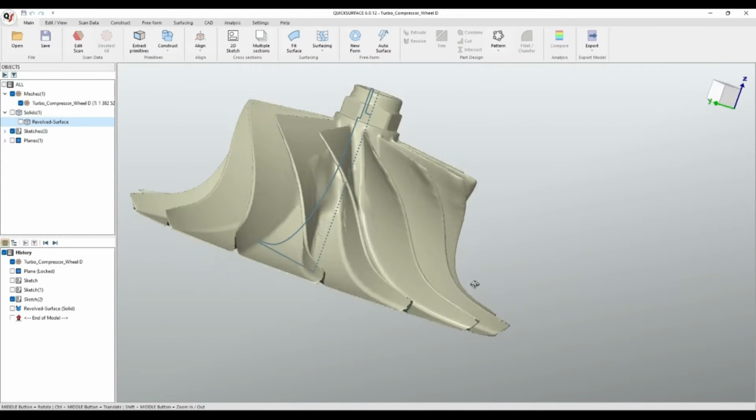It's going to ask us to determine the area to be created. We would choose an area that has a good scanned surface, so that the resultant surface is smooth. Once you create the surface, we're going to expand the selection by 70% to make it easier on us later on. Check the analysis box to see how the surface created deviates from the scan data.